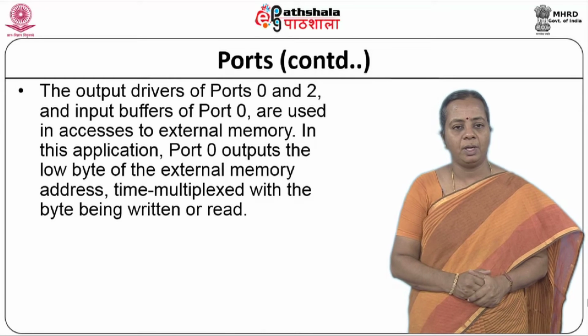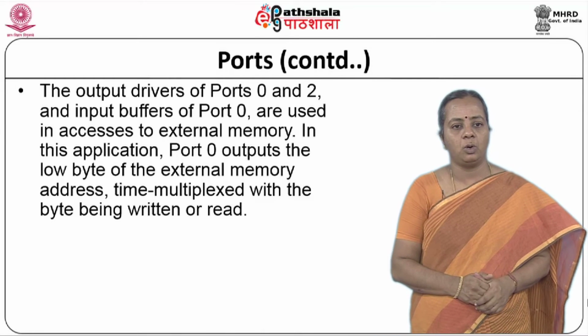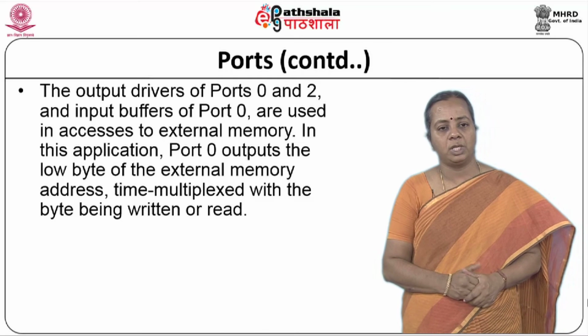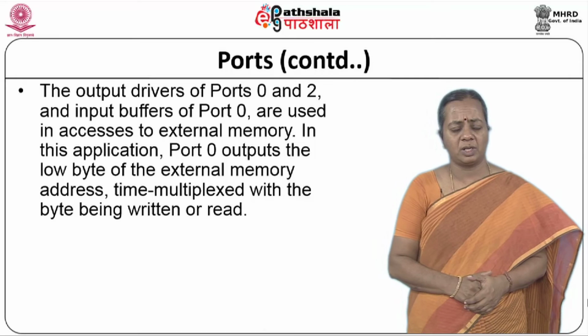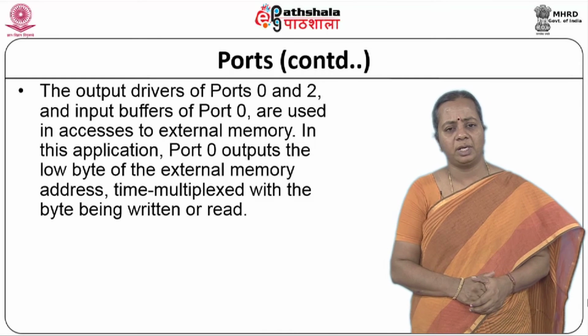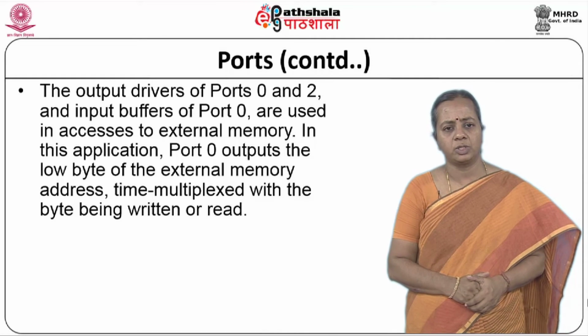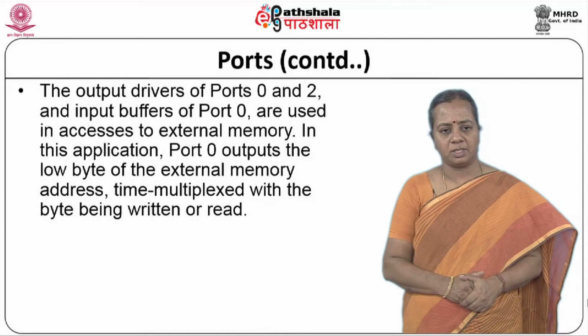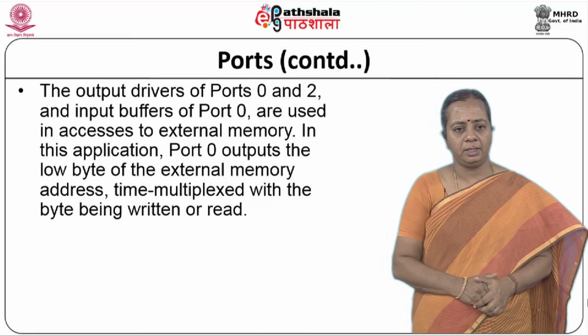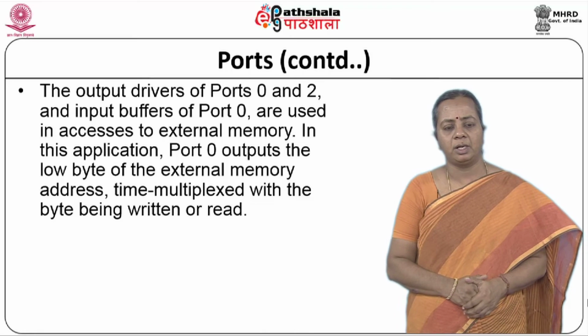So, we can use port 0 and port 2 for sending data as well as reading data, and for sending your address, for all those purposes. Port 0 outputs the lower byte of the external memory address, and the time-multiplexed byte is being written or read.